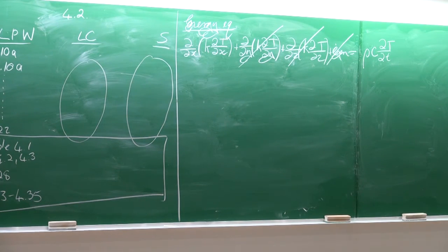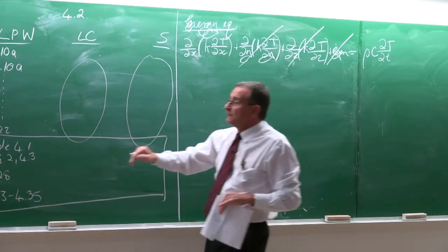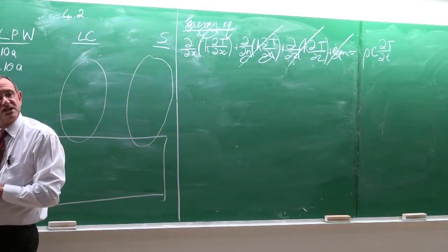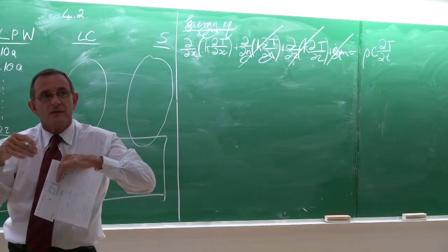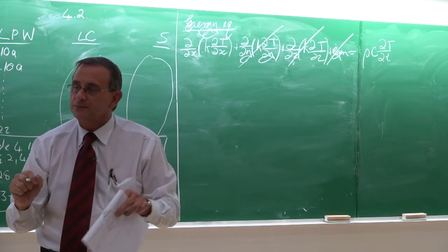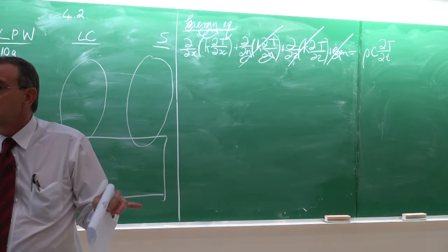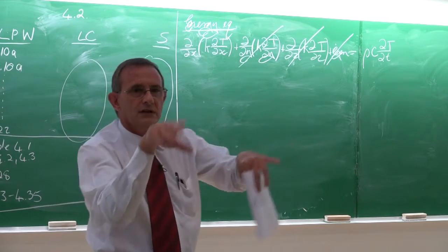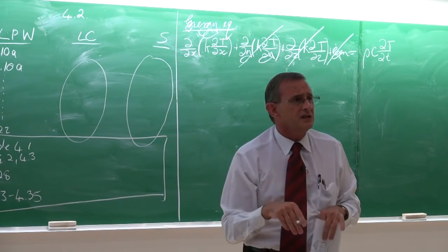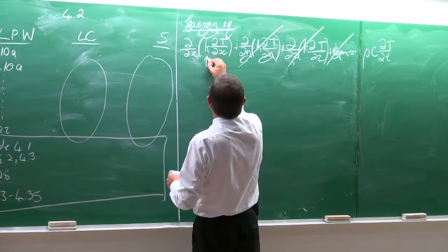When is that relevant? It is relevant if we have a material like a composite material where the thermal conductivities are different in different directions. But to start off, we're not going to work with a complex material like that. For the materials we use normally, the thermal conductivities are the same in all directions. So this k is also constant.